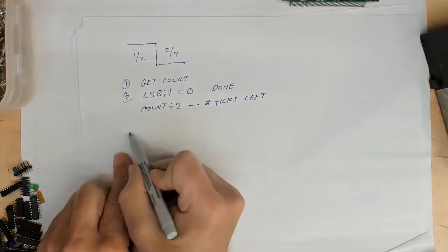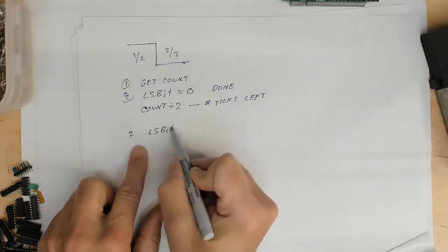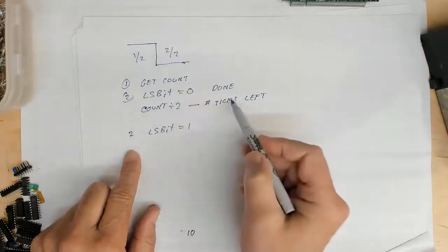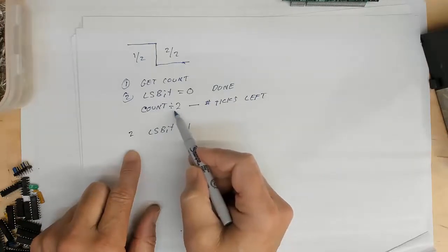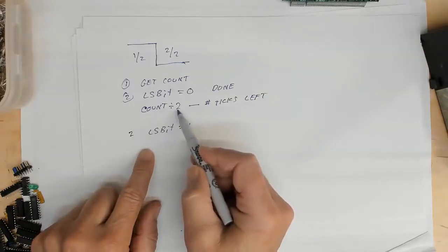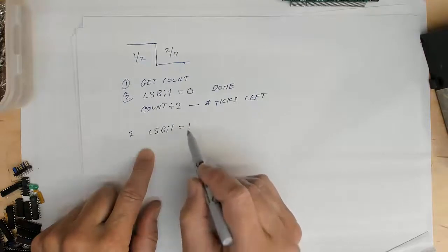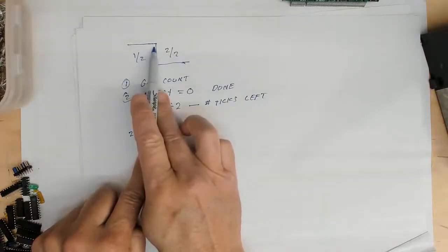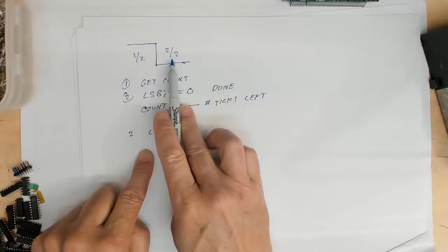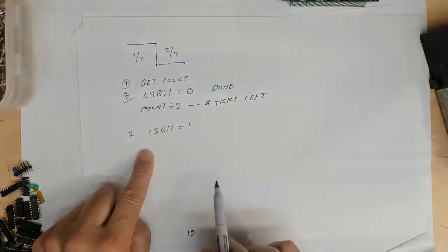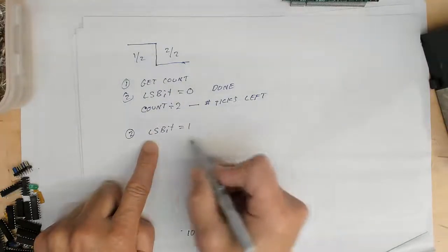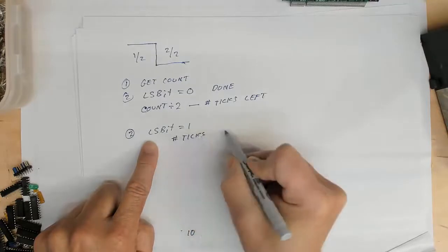But now, if the least significant bit is equal to 1, we will take what the count actually is, all 14 bits. We will divide that by 2, and we'll divide it by 2 by rotating once to the right. And we will get a value that tells us how many ticks are left in this half of the count, but this time this half of the count is the first half. Either time, we're finding out how many ticks are left in the current half of the count. It's just whether we're in the first half or the second half. So least significant bit equal to 1 means we're in the first half of the count. We do the same thing to find out the number of ticks left in this half.